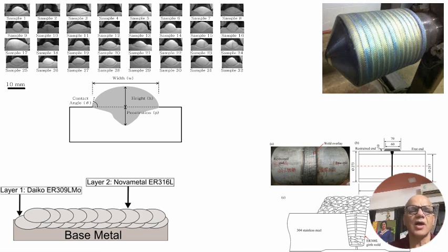Hard facing will have a crack initiating from there. Built up, if it is there, it is not going to be a sound metal for us to have a built up. If it is for lamellar tear, then that could be a potential point acting as a notch. So a lot of care is required when we are going to do this build up.